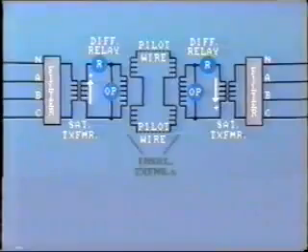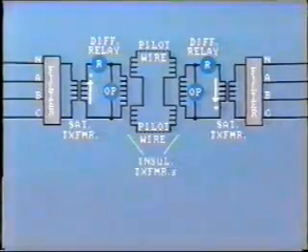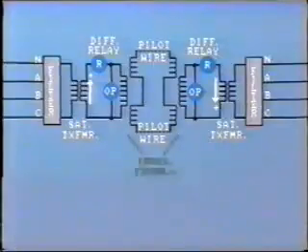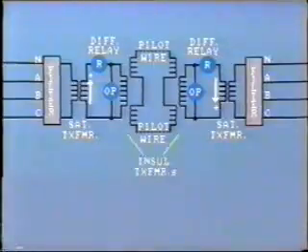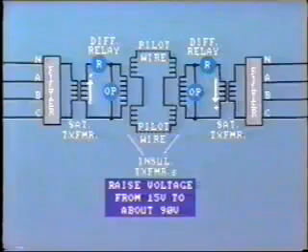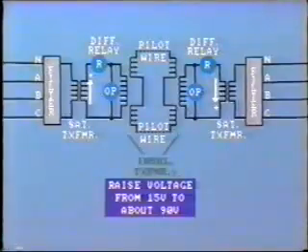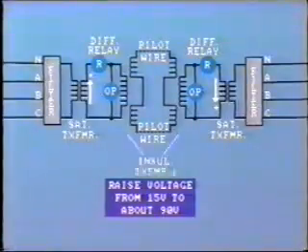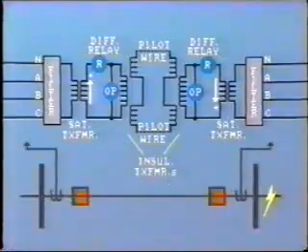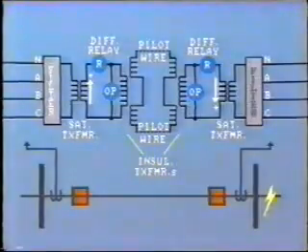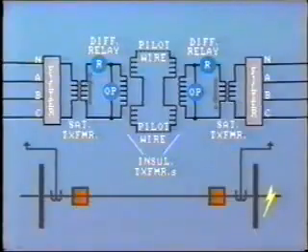Usually, the pilot wires are insulated from the relay circuit and the CT secondary circuit by an insulating transformer. At the same time, this raises the voltage from 15 volts to about 90 volts, so providing for more positive circulation of current. Where the fault is external, that is, a through fault, the sequence filter at this far end will produce a terminal voltage, which is of the opposite polarity.